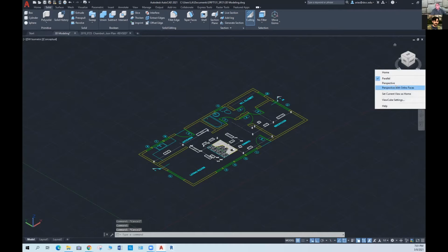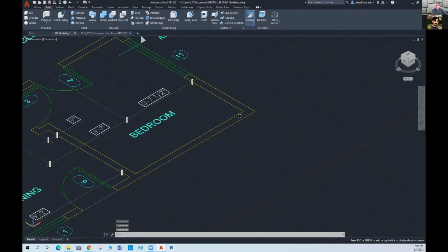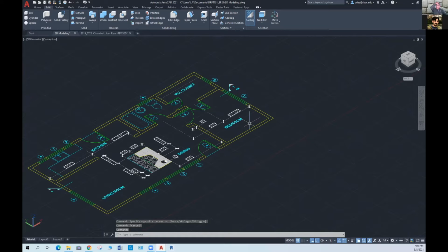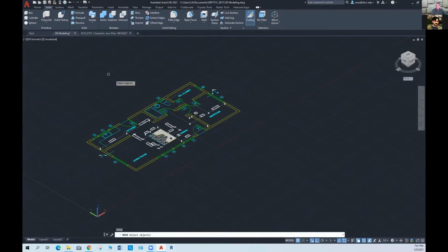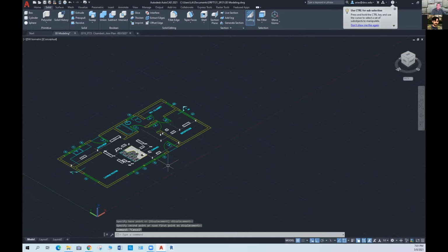Let's define this as the home. And these walls on the sides are 6 inches walls. And so one thing I can do to start creating this geometry would be to use the polysolid tool, right? And this is kind of the workflow that I'm thinking that you can use, is to bring your floor plan into the 3D drawing and then start creating geometry. First, I'll create the walls, then I can create the floor, and then I can create a roof. And there are all other ways of doing this as we continue to work.